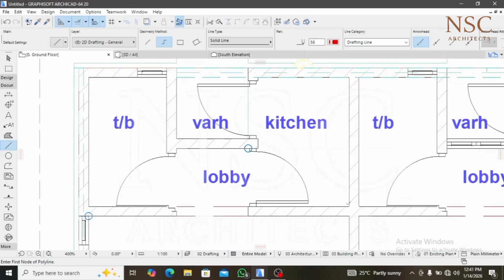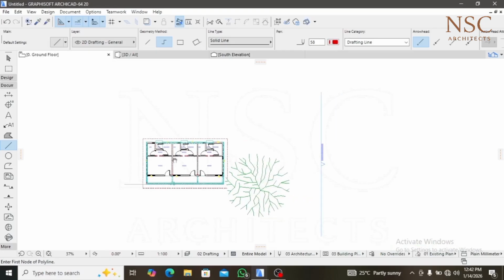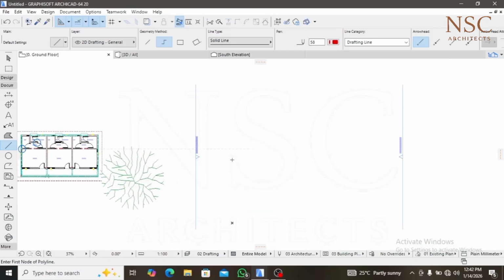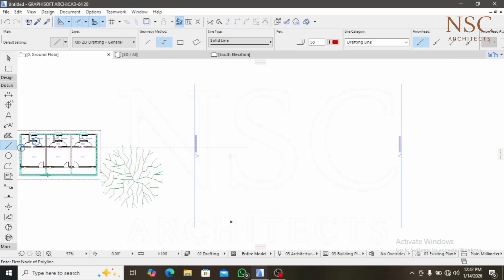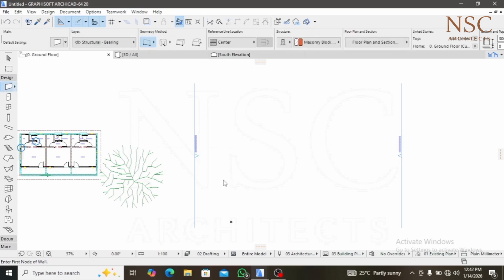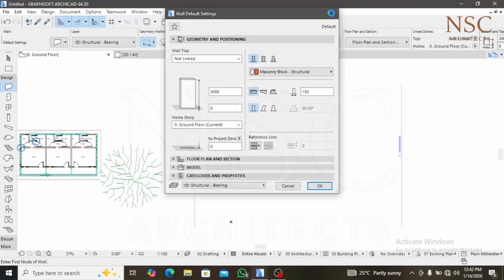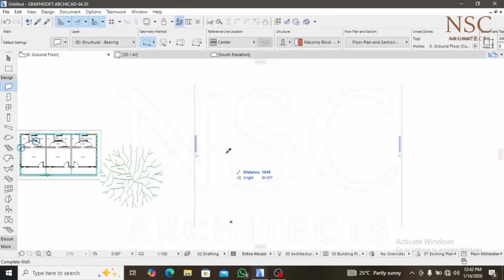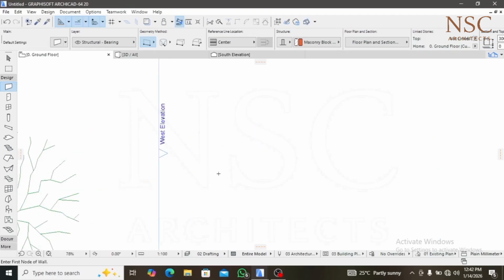So now let's start. Exercise begin. We would be starting with a wall. Let's just draw a wall, our 150 wall. My mouse is messing up. If you want this to be in a straight line while you drag it, you hold your shift. You see, it won't shift once you leave your shift, but hold your shift and you now drag.